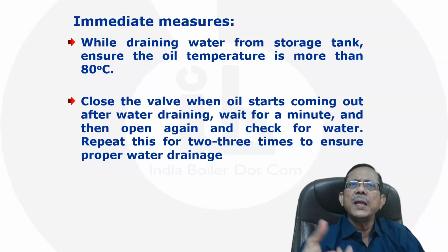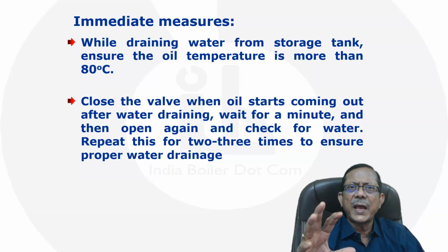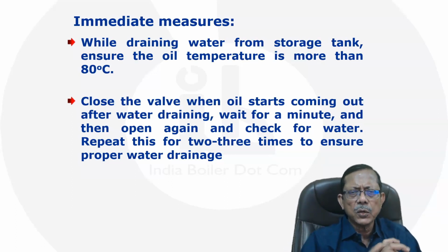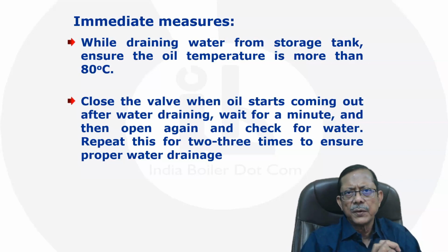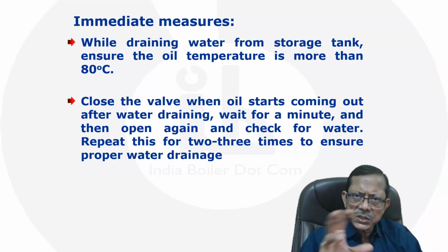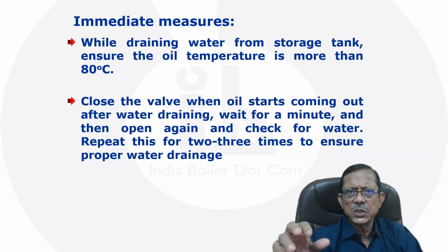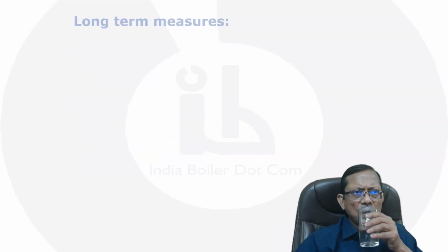Wait for a while, then open it again, right? So throttle the valve a couple of times and see whether further water is coming out or not, because in my experience, later on more water is likely to come out of the system. I have experienced it myself in a couple of storage tanks, right? So close it and then open it, and do it at least 2 to 3 times to ensure that the water is getting removed properly. Okay,